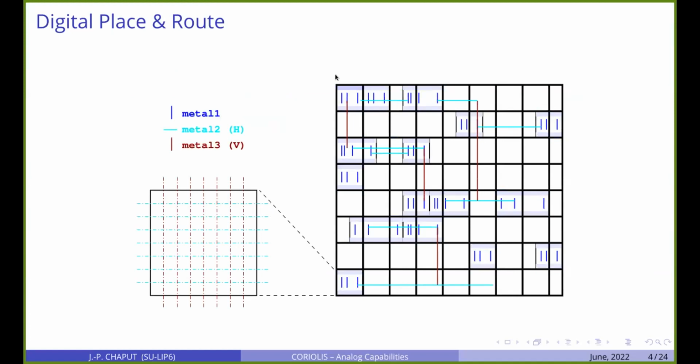The routing is divided in two stages: the global routing and the detailed routing. And this articulates around the GCells. What you see here is a close view on the left of one GCell, and a GCell is just an abstraction of a small part of the design, because the design is usually too complex to manage directly. So we perform global routing, which is routing over the GCells only. We consider only the GCell as one point of the grid.